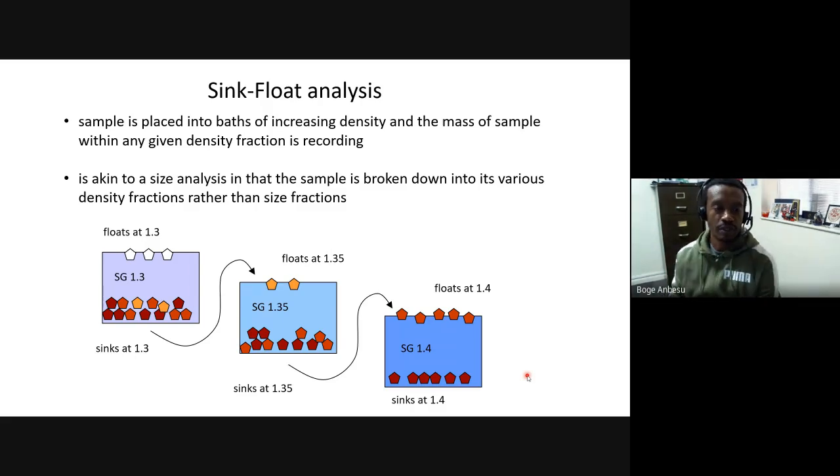When you think about it, this is actually very similar to what we did for particle size distribution, where you had a sieve, and on top of that maybe a coarse sieve size. Particles passing through that sieve are collected in the next one. If they pass through that, they will be collected in the next one, and so on. At the end of the day, you can determine the particle size range depending on the sieves you used. So this is very similar to what happens in a sieving process.